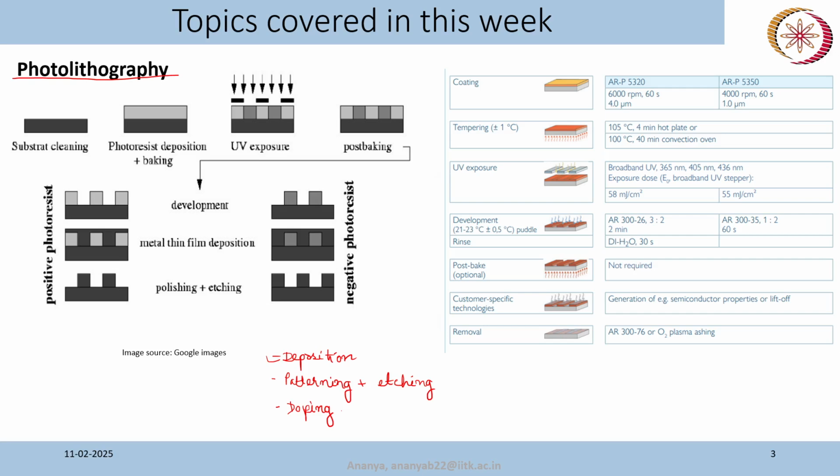Mainly, we know how we can do photolithography on a silicon substrate. Everything is well established, so we often use this technique for fabrication of MEMS based sensors and other micro devices in micro dimensions. Okay.